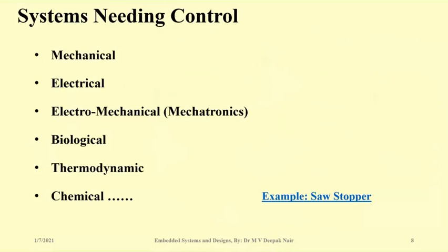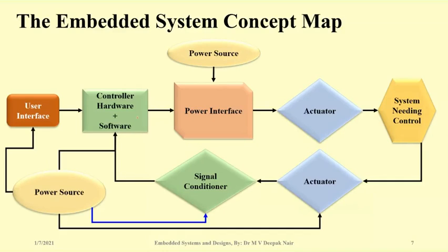Now, Sir, why do we need two separate power sources? Why can't we use a single source? This one is just to increase the power of the microcontroller's output. Remember, this is just increasing the power, for example, when you are using a switch or a high power supply to drive the actuator. But here, this power supply is, for example, for the keypad.